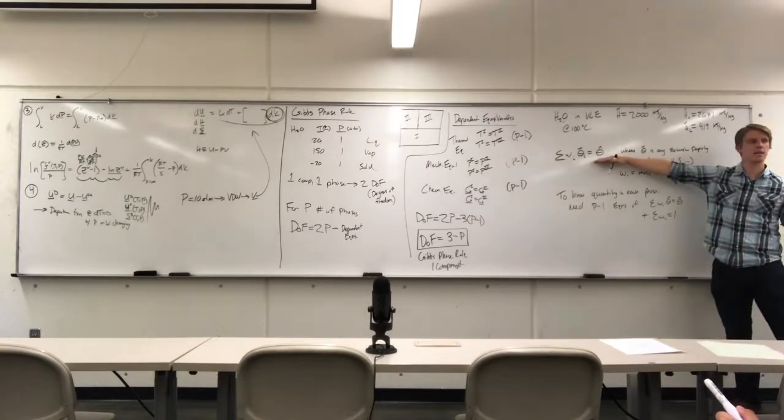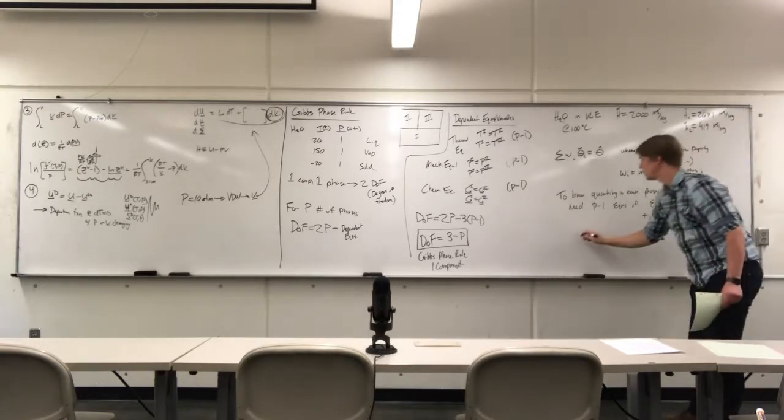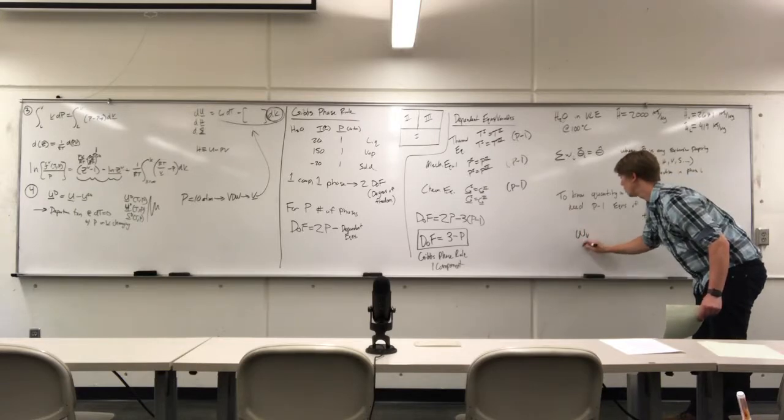We can apply this expression here, where we're basically taking a weighted average of how much the liquid enthalpy is bringing to the mixture and how much the vapor is bringing to the mixture, in which case we can then solve for the weight fraction in the vapor and liquid phases.